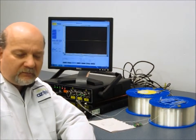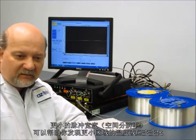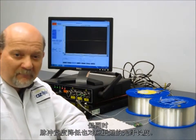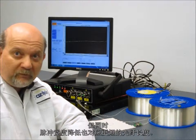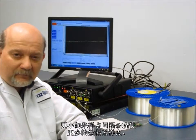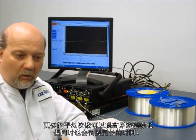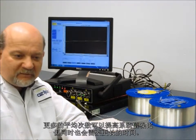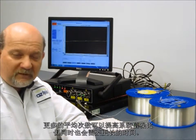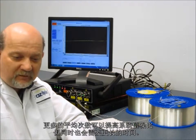The shorter the pulse, the shorter the distance over which you will detect changes in temperature. However, you are limited by the total length of the fiber to a certain minimum pulse width. The shorter you make the spatial steps, the more data the instrument has to gather. The more averages you take, the more accurate the measurement will be compared to the noise signal. But again, more time taken to take these measurements.